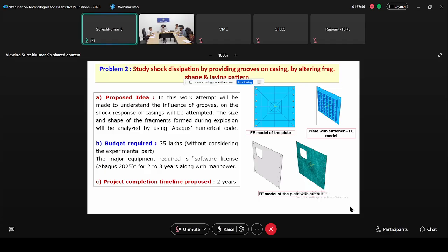Suppose we want to make an experimental validation for the numerical simulation, because right now we are working with the SPH algorithm, sir. We are using the smooth particle hydrodynamics algorithm for the bird hit impact for GTRE also. Even the dynamic simulation is in the preliminary stage. So definitely we can do the shock simulation of the target for various configurations using the numerical methods, sir.